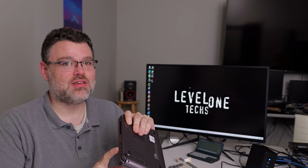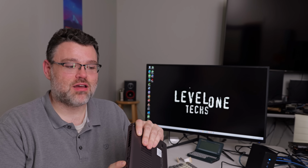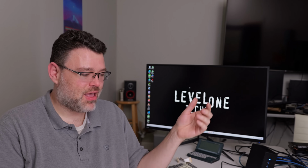A lot of these Oculink connectors are only rated at 1/10 of the number of insertions that their USB-C counterparts are. Similarly, the cable Minisforum bundles with the G1 is intended for use internally inside a server. It was not intended to be used outside of a nice protective chassis. Sure, it's got a braided exterior, but this thin plastic braid and the foil wires underneath are really all that separates this thing from chaos. This connector was not meant to be bent or pulled, or inserted more than probably 50 times.